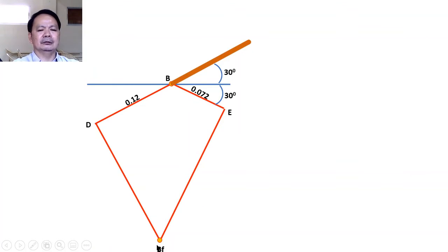Right? So at first glance, it looks a bit difficult, but let us make the solution simple. And to make it simple, it's just a matter of creating a series of triangles. So, let's start by drawing a horizontal line passing through BF. Passing through BF, a horizontal line. And then we draw a vertical line passing through D.